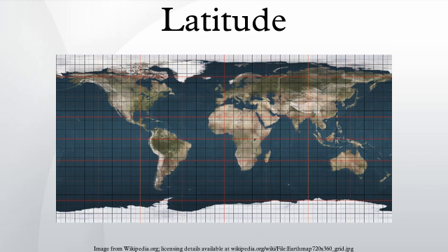Many different reference ellipsoids have been used in the history of geodesy. In pre-satellite days they were devised to give a good fit to the geoid over the limited area of a survey, but, with the advent of GPS, it has become natural to use reference ellipsoids with centers at the center of mass of the Earth and minor axis aligned to the rotation axis of the Earth. These geocentric ellipsoids are usually within 100 m of the geoid.